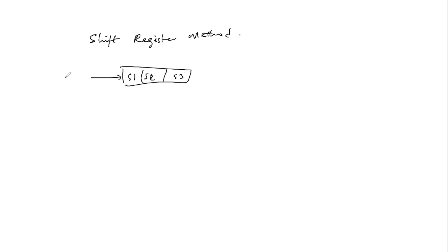So we have the input this way. Convolution codes are usually generated by transmitting a data sequence through shift registers, which has 2 or more sets, in this case 3 sets of registers or register taps, filters, with each set transmitting in modulo 2 adder, okay? So they could combine using a modulo 2 adder.